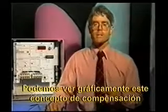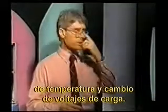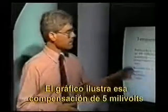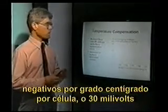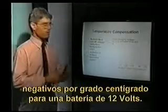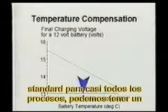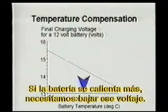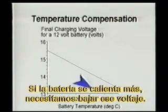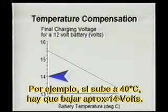We can take a look graphically at this concept of temperature compensation and changing charging voltages. If we look at our graph that illustrates this negative 5 millivolts per degree C per cell sort of compensation, or negative 30 millivolts per degree C for a 12-volt battery, you can see that at 25 degrees, the standard rating temperature for most all processes, we perhaps have a voltage cutoff point of 14.5 volts. If the battery gets hotter, we want that voltage to go down. For example, if the battery rises to 40 degrees, we might be down around 14 volts.